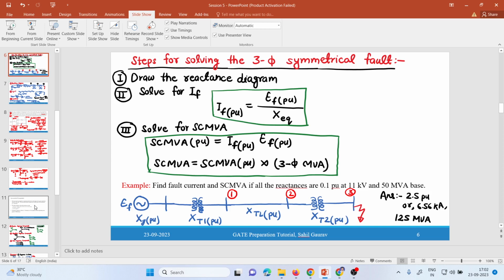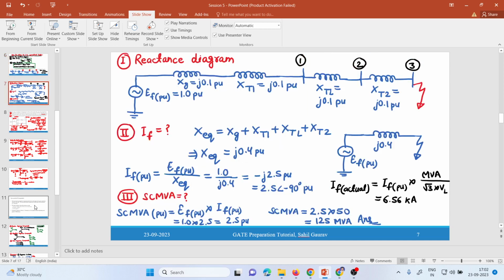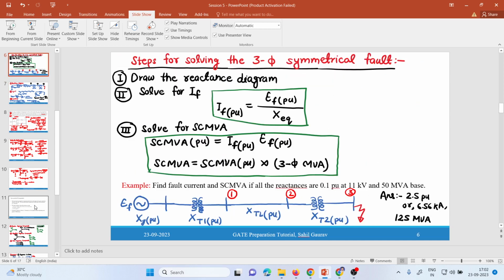In this chapter, I have discussed only symmetrical fault analysis, and in the last part, I discussed the symmetrical components. Before we discuss unsymmetrical fault analysis, you should know how unbalanced voltages and currents can be converted into three sets of balanced voltages and currents. So you are asking about LG, LL and double LG faults. Yes, sir. These have different expressions. In general, whenever ground is not involved, the zero sequence reactance will not come in the expression. Only X1 and X2 will come into the expression.